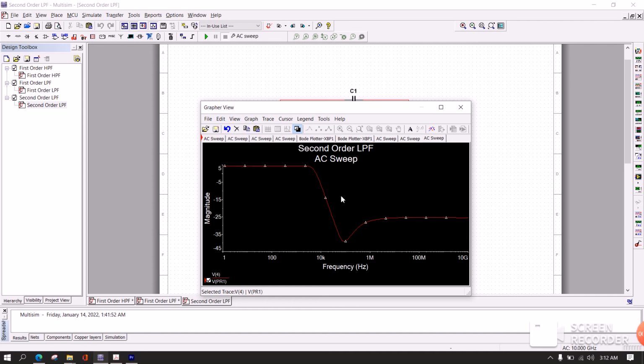Higher frequencies are attenuated more severely by the second order filter. The Bode plot of this type of filter is similar to that of the first order filter, except its fall off is faster. Each time the frequency doubles, a second order Butterworth filter reduces the signal amplitude to 1/4 of its original level, resulting in a power decrease of 40 dB every decade.